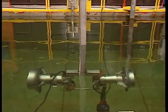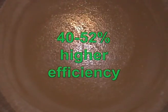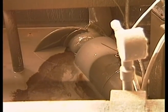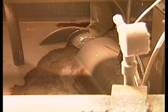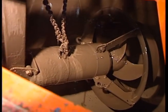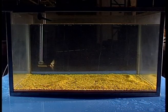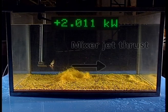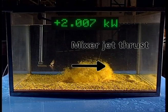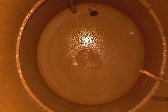Our tests show that a Flygt agitator has between 40 to 52% higher efficiency than the competitor. This can also be translated into the simple fact that you will need a much bigger agitator from a competitor to achieve the same mixing results in your drilling mud tanks. The next time you compare a Flygt agitator with one of our competitors, it is important to look at thrust performance and efficiency, and not just the size of the motor. Otherwise, it will not give you a true picture about how well the equipment mixes the mud. What you see is not always what you get.